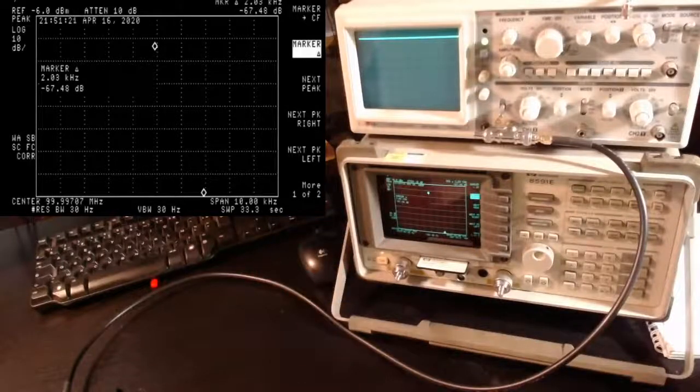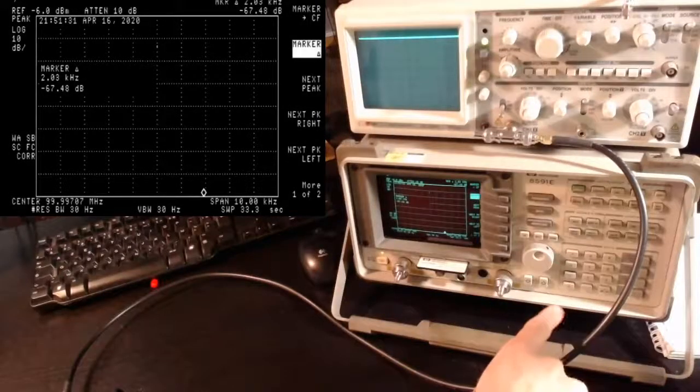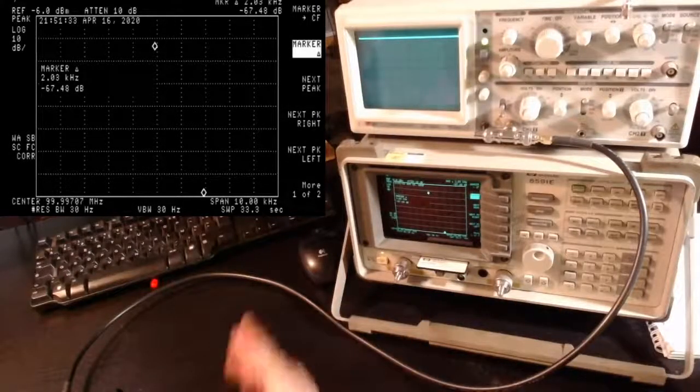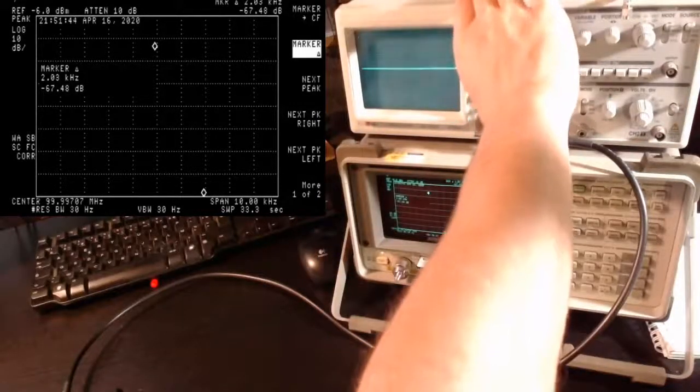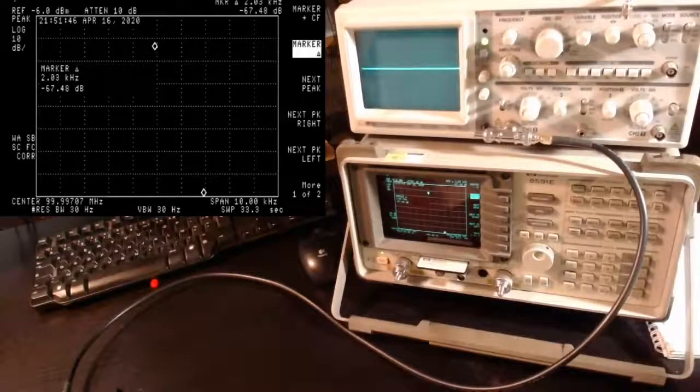So the HackRF, even when it's not outputting anything, has a DC component, as I mentioned before, 1.5 volts. So it was really important to have a DC blocker to block this component. I couldn't find a way to remove it, so I think that the firmware of the Portapack always does that, so just be careful. Anyway, let's move then to the AC component, so we don't need to worry about anything.